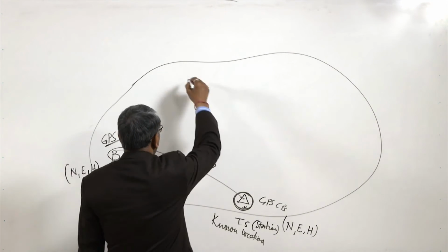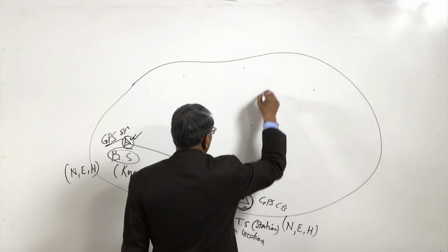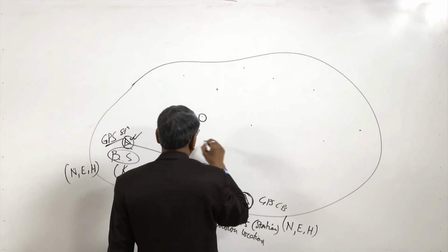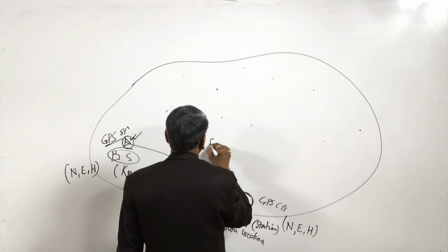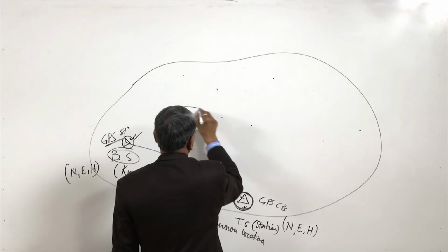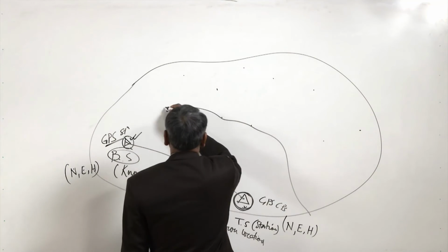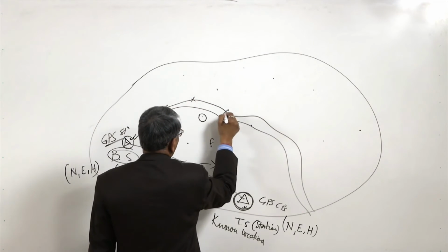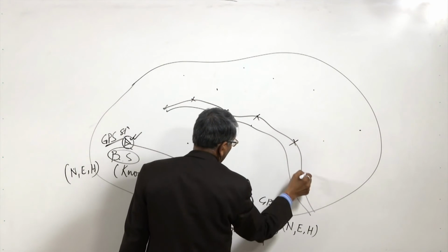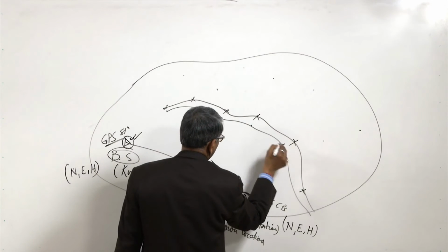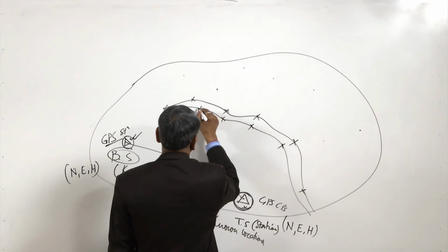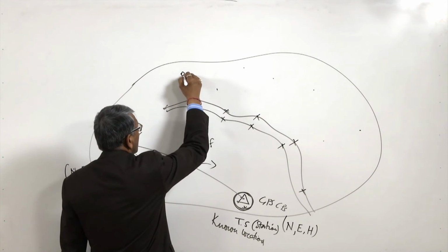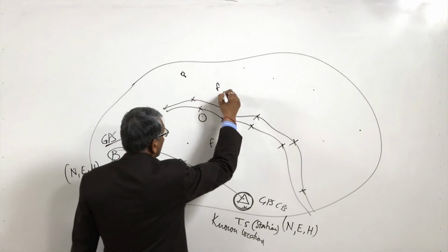And then any other points, suppose there are so many other points, objects which we will be able to identify, like trees, telephone line, road corners, like these points. We will note down, using the total station, corners, salient points, and then there may be a tree, telephone line.